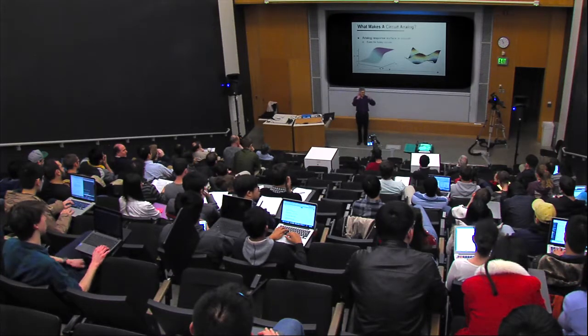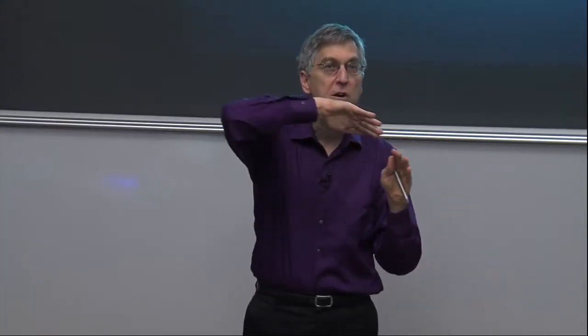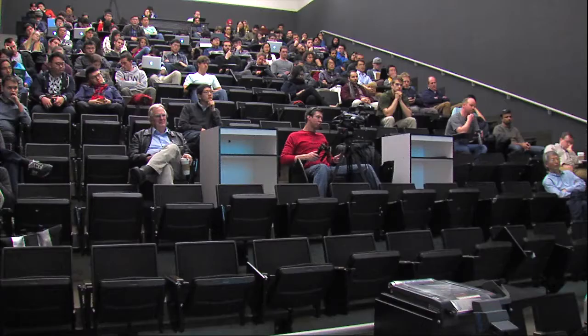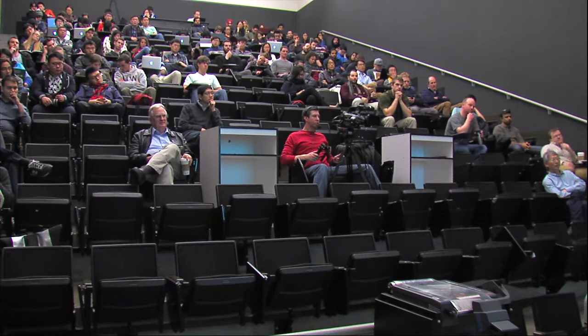So the thing is, digital results are not smooth. That is, an incremental change in an input can make an enormous change in output. That's what makes it digital. What makes it analog? Continuous. Right. The output surface is continuous. An incremental change in input causes an incremental change in output. What that says is all analog circuits have smooth output surfaces. That's fundamentally what makes a system analog. So we should be able to leverage that in the way we think about analog circuits.